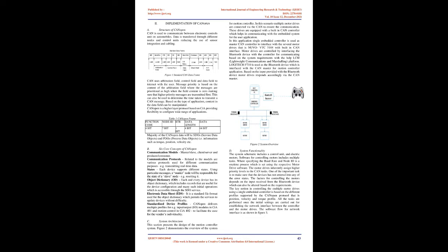Nevertheless, CAN defines the physical and the data link layer, with no traces of an application layer. Therefore, the CANopen protocol approaches in order to eliminate this gap between the application layer and the user. CANopen in motion control for communication can not only resolve difficulties with the connection, but also increase the reliability of the information transmission, instant response, tuning, etc.